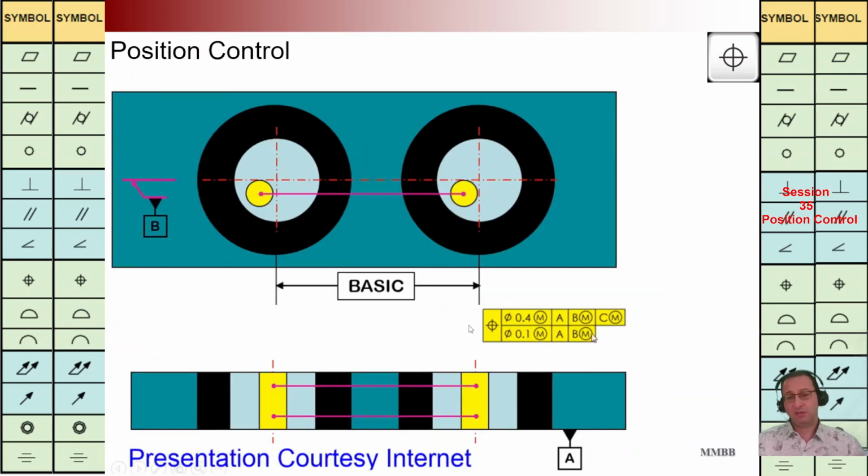In the last step, if you are going to add B here, what happens? It means those two small cylinders should be perpendicular to A, and also we are going to have an offset of 0.1 with respect to B. These two small cylinders should be in contact in the same situation with respect to plane B.